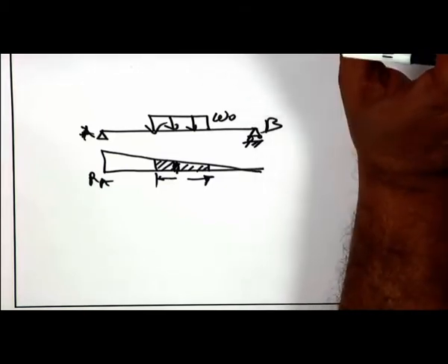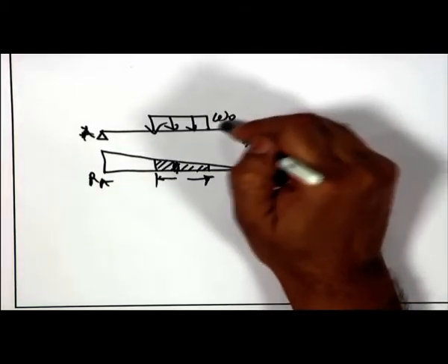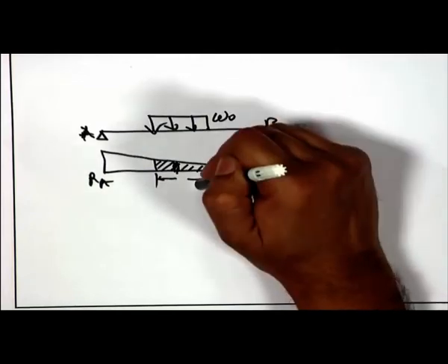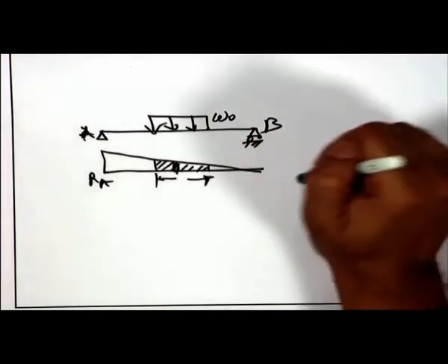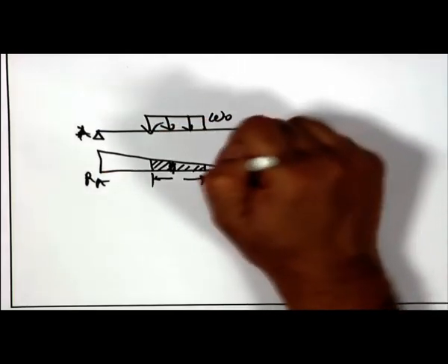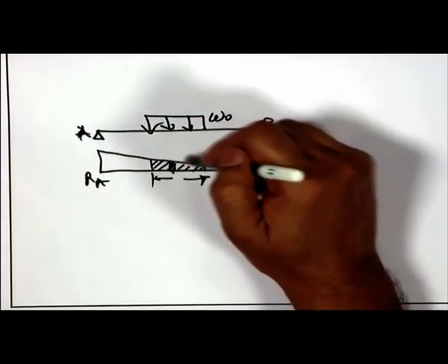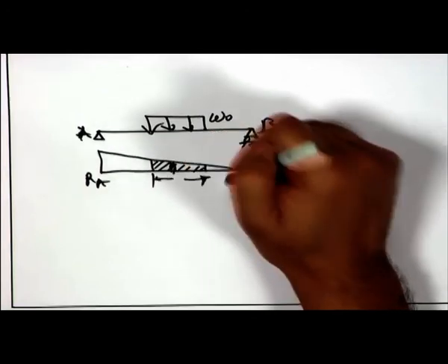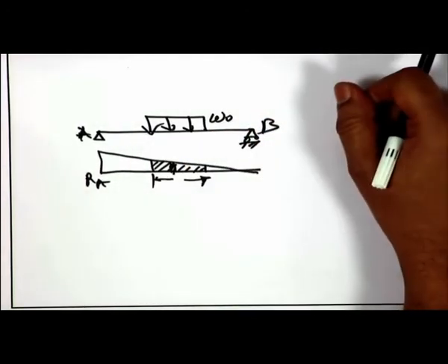For uniformly distributed load, your omega 0 comes out of the integral. So, you are left with the geometric entity of finding the area under the curve. So, area under the curve is very simple. You can integrate with an elemental area or you can use the geometry. Any other questions? You can also confirm if the lecture was okay.